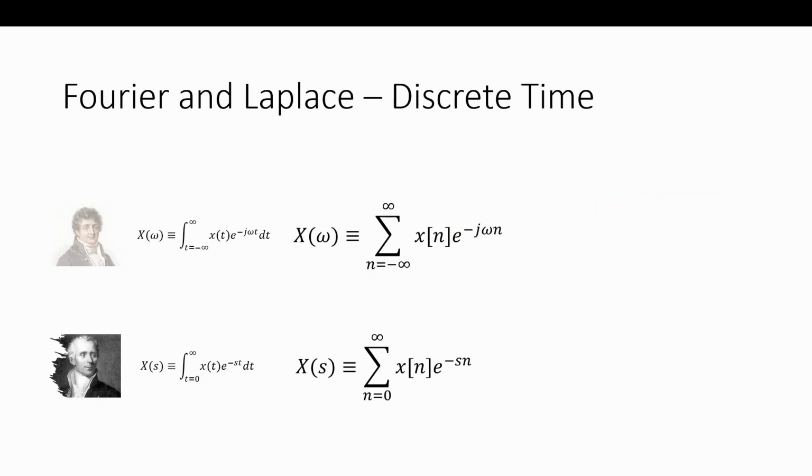So Fourier and Laplace, as I introduced, were the continuous time, the continuous time waveform, the analog waveform. If we go discrete, integrations become summations, right? So a moving summation and adding an accumulator, that's an integration, a digital integrator. So we're accumulating. So this is saying, hey, we're going to sum every result, every product.